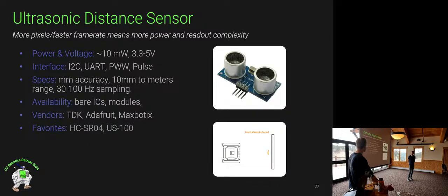I think pretty much everyone has seen an ultrasonic sensor, especially if you went to the embedded systems workshop yesterday. These work by sending out a ping of ultrasonic 50 to 100 kilohertz sort of signal, and then that reflects off an object and comes back. So you don't have to worry about light interference with these sensors, but you do have to worry about the softness of the material, the shape. So there's kind of orthogonal noise and things that impact the performance. So combining sensors together might be a way to improve robustness. Where one sensor fails, you can pick up and use the other.